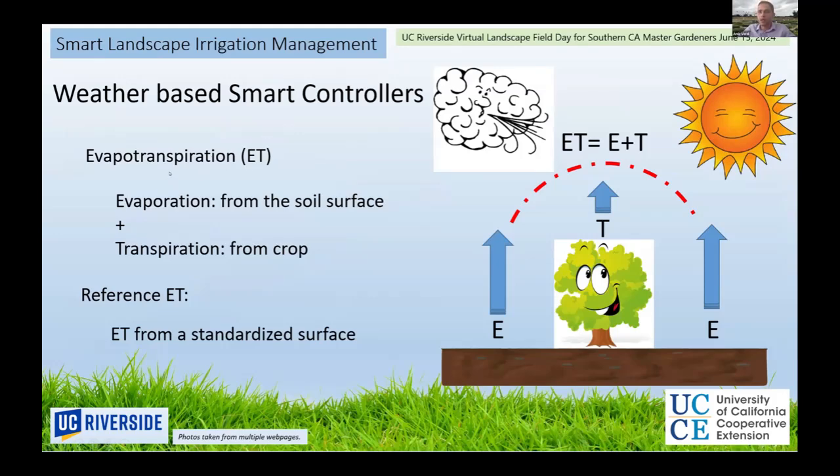They are going to measure or estimate evapotranspiration, which is a combination of evaporation from soil surface and transpiration by plants. We usually combine these two terms and call it evapotranspiration. There are different methods to schedule irrigation. One method that is even widely used by researchers is ET-based irrigation scheduling. So what we do is that we measure reference evapotranspiration, which is evapotranspiration for a reference crop.